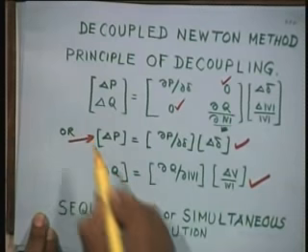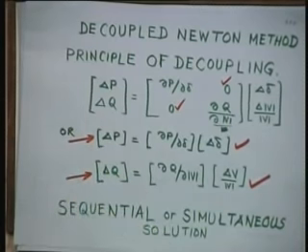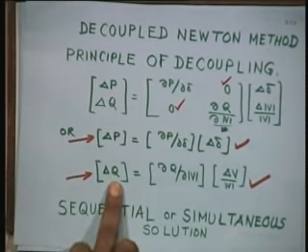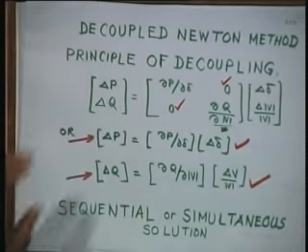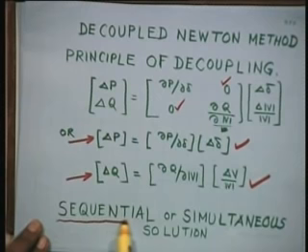In fact, you can solve the real power problem independently of the reactive power problem. If you are not interested in economic dispatch or economic operation of the power system, you are only interested in minimization of losses, solve only the reactive power problem. But if you are interested in both, then either you can solve in a sequential mode or a simultaneous mode.